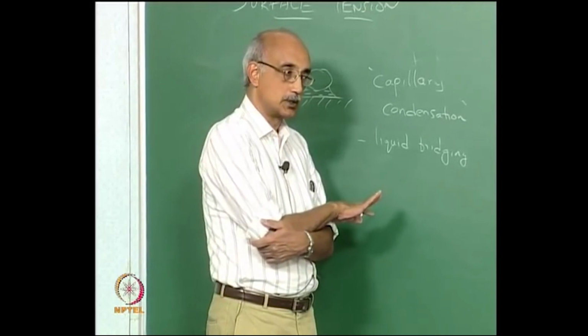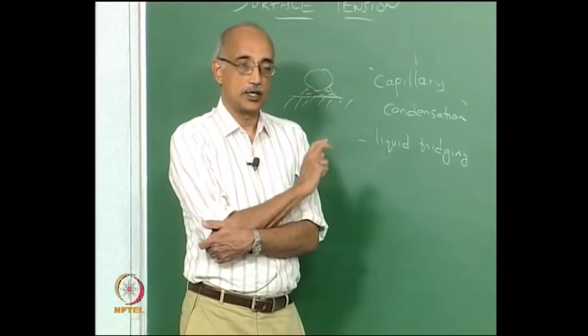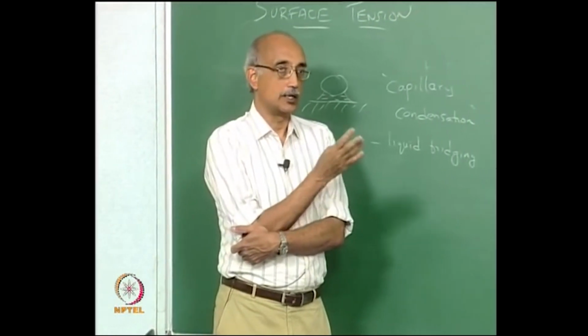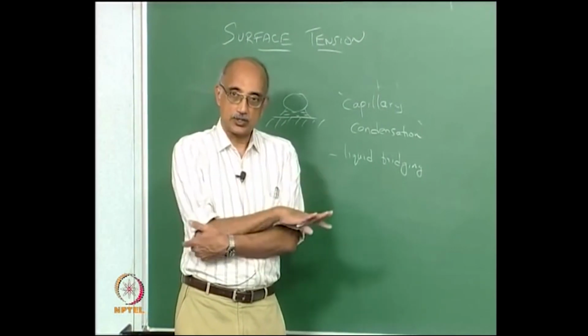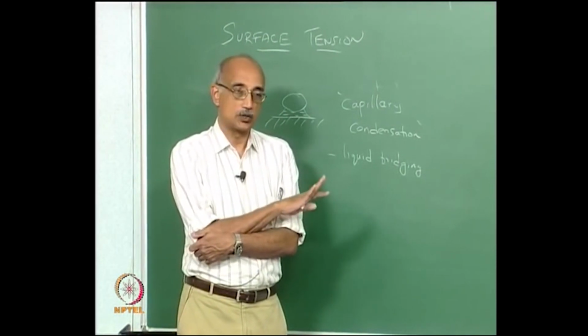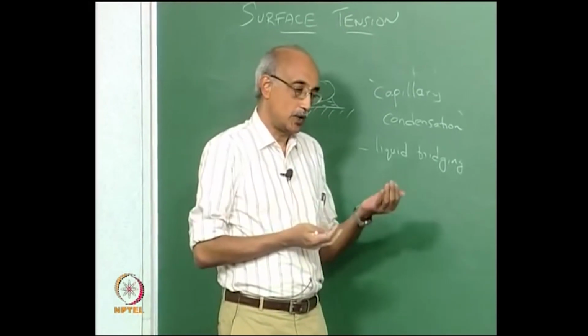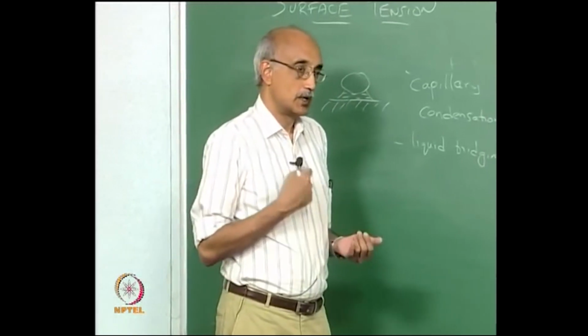So, the Coulombic forces and the image forces are all significantly weaker where water or a liquid is the medium. There is an immediate reduction in the electrostatic contact potential forces also by a factor of about 80. So, when you take a particle-surface combination and immerse it in a liquid, everything is reduced.